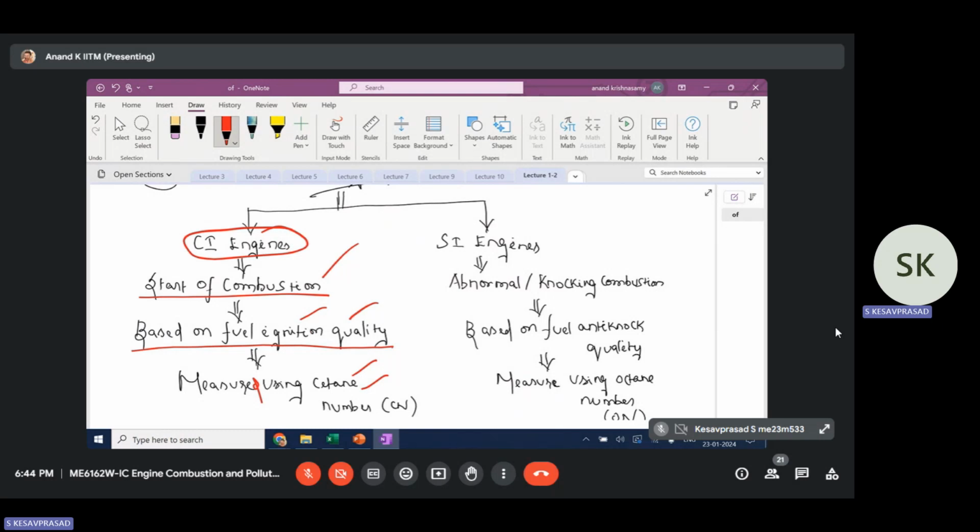That is one problem. But a more severe problem is that knocking can happen, because once you inject the fuel, it has to start ignition as quickly as possible. If the ignition event is delayed, if the delay time is so long, what will happen? You are injecting more and more fuel during the delay time. Once the ignition happens, this larger volume of fuel injected and accumulated in the engine cylinder will start to combust and release a large fraction of thermal energy, and that may eventually damage the engine.